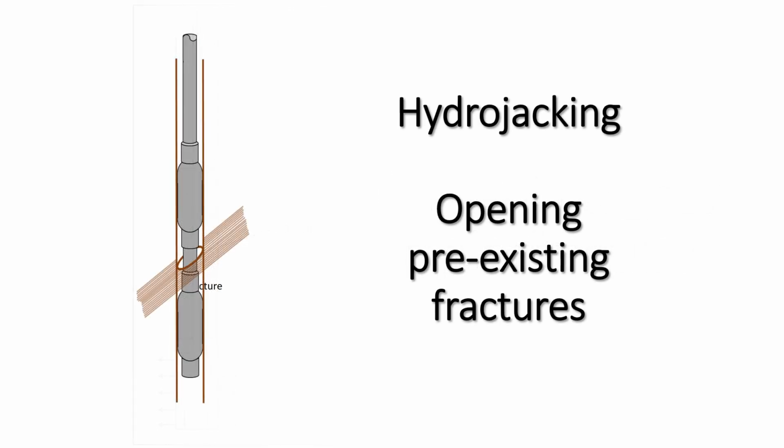If the rock mass is fractured, it may be possible to use hydrojacking to measure stress across a joint. This involves using packers to straddle a fracture within a borehole. This straddle zone is then pressurized until flow indicates a fracture has opened. Pumping is then halted and the pressure decline within the hole is monitored. Fracture closing is determined by similar processes to that used for hydrofracture analysis.